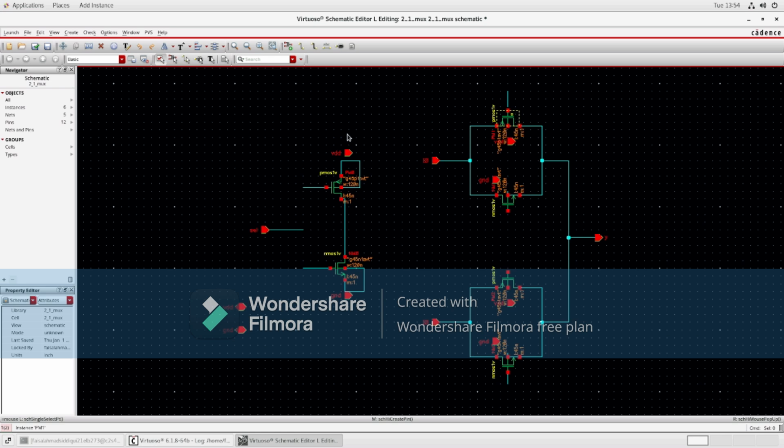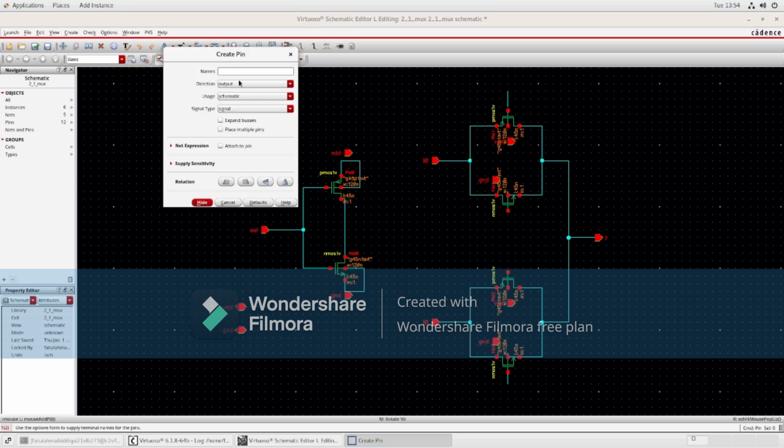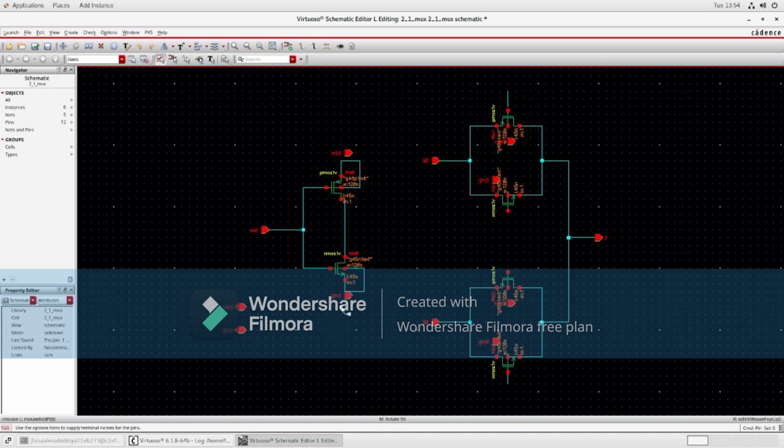Now we have to connect the inputs of the inverter. So again, click on a wire, connect these two inputs. Alright, and we have already joined the PMOS and NMOS with their bodies. We will click here and select a wire, and we'll join. This is a must to join. Okay, and here VDD and ground have already been taken. We'll go here, write VDD and ground, and give them a direction. Just hide them and we will put them here.